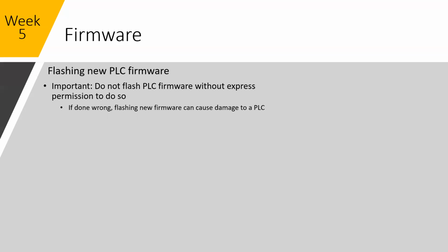They used to all come with firmware 15 on them, maybe 16. They might come with 20 or newer. Some of the new controllers can't be downgraded past a certain level, and some of the older controllers can't be upgraded past a certain level. When I say level, I mean firmware version. That information you're going to have to look in the different manuals. There are tech notes all over Rockwell's knowledge base. But if you don't need to do it, I wouldn't.